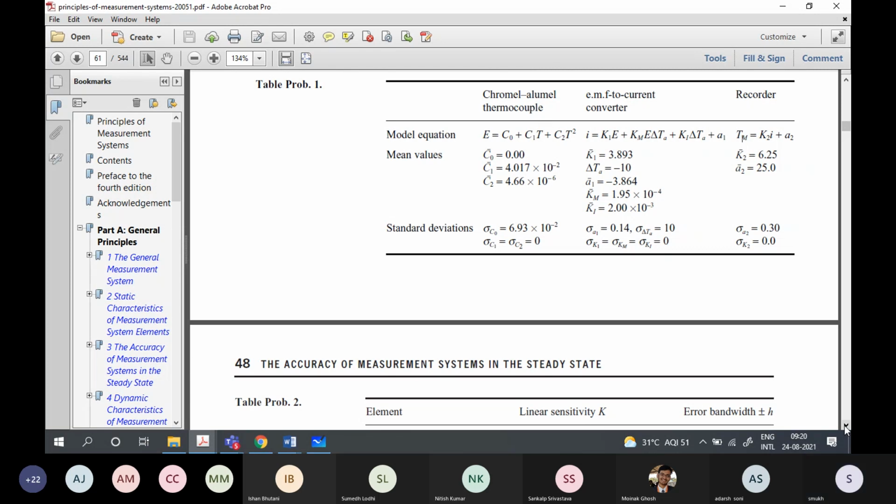So the overall variation in the random variable is the RMS value of the others multiplied by the gains. That is the way to do it when you are trying to calculate sigma. But when you are trying to calculate worst case, then you have to literally find the worst case. So here, everything is positive, so the worst cases are always for positive values.